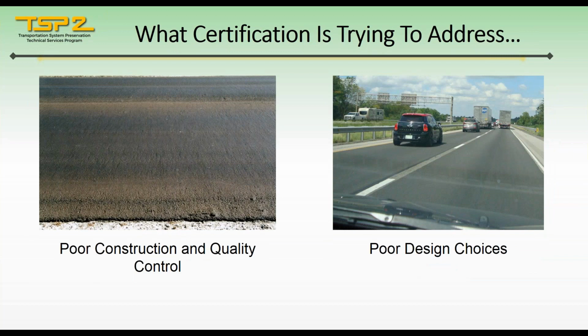In the next photograph, we have a poorly constructed cape seal. And on the other picture, we have a microsurfacing that was constructed in Illinois in 2015. The designer wanted to try and stretch their money by leaving the longitudinal construction joint and raised pavement markers untouched. Illinois still has a problem with obtaining density at the longitudinal joint as one of the main causes for rehabilitation. Leaving an area for water to pond and penetrate a porous surface will only accelerate this deterioration.